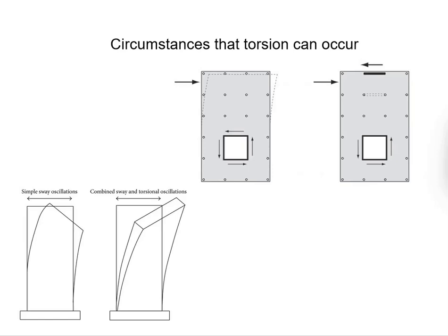To make it a braced structure, you need members with strong resistance to the lateral loads, for example, shear walls or core walls. With the assistance of the shear walls or core walls, you may design the columns as braced members, which will be more economical and easier to design.